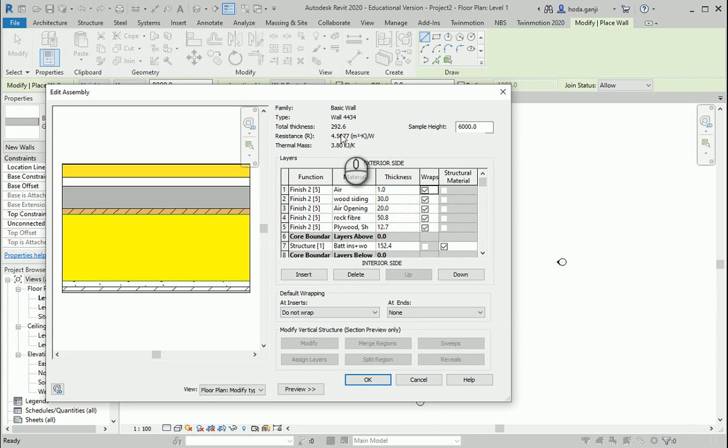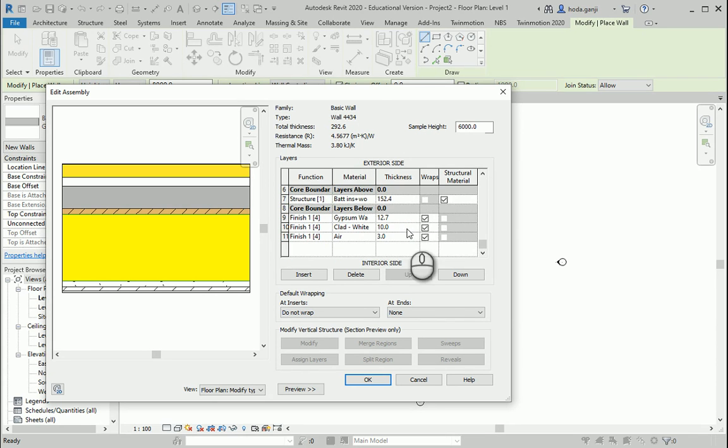So I'm gonna put this on 1 instead of 0.75 millimeters. And in order to keep consistent with the R resistance for the air on the other side, I'm gonna reduce the value here maybe to 2.8 or 2.7. Let me see how 2.6 works. 4.55 and 4.55, 2.6 seems to work the best. Okay, so it seems about right. The thicknesses are correct. It's all good. The total thickness of the wall is about 30 centimeters, which is very reasonable.